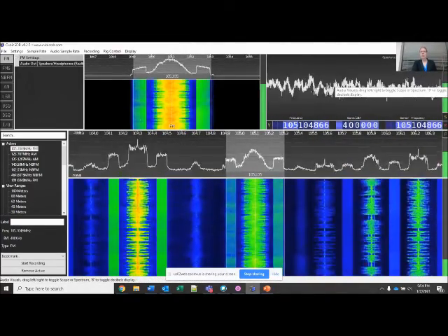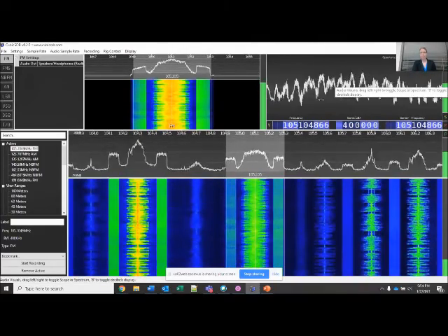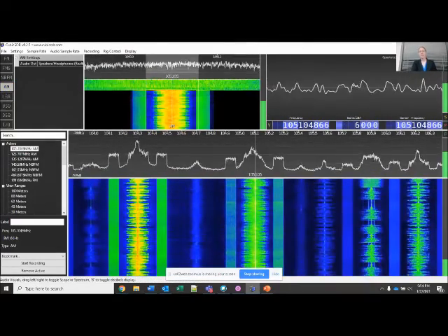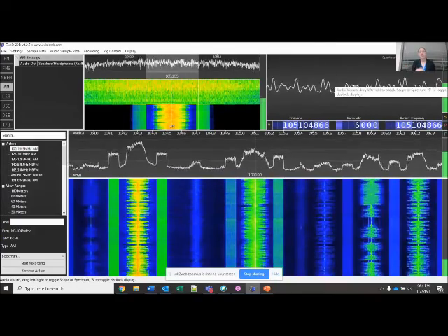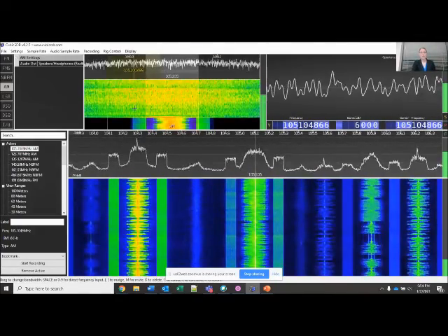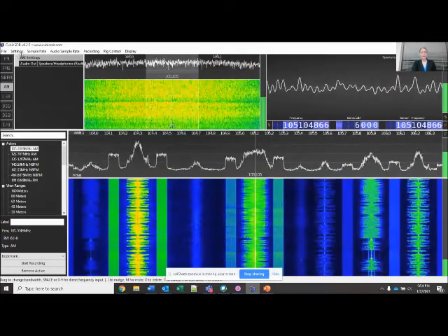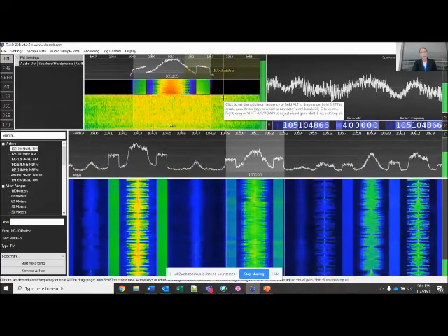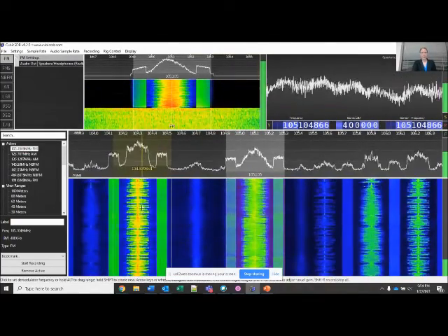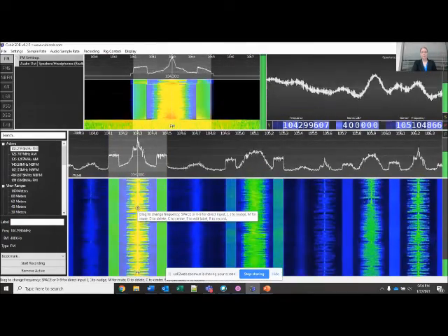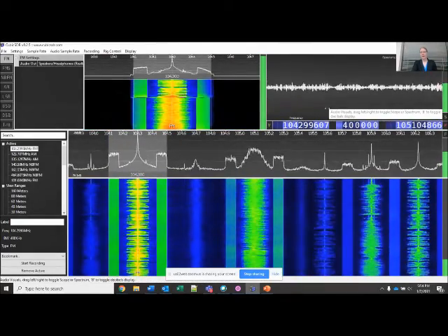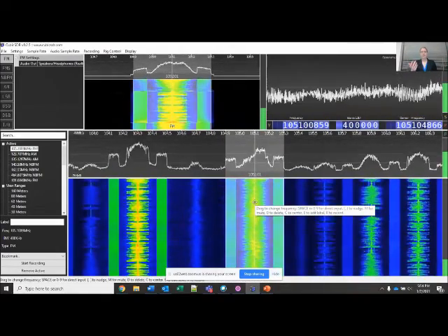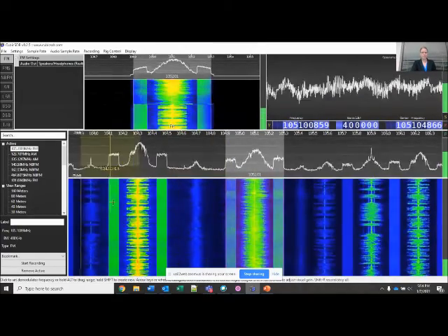This up here in the upper right is really showing the modulation, because look what happens when I switch this to AM. All of a sudden it's just junk, and I can tell you on my side that the audio has changed to just complete static. So you can see when you're not demodulating it properly, this goes from being an intelligible signal of people talking to just noise. With that, I can change from one station to another. And you can see this one's a lot more human voice talking, whereas the other one had a little bit more music, and you can kind of see the difference, a little bit of richer frequency content.